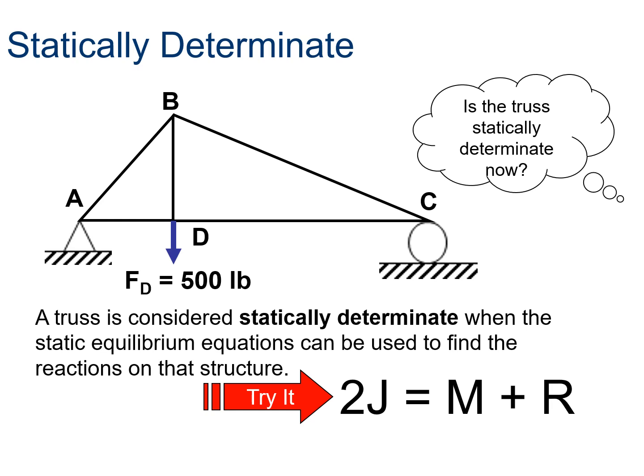now you have the same number of beams, 1, 2, 3, 4, 5, so M is equal to 5. And we have the same number of joints, 1, 2, 3, 4. Now the difference here is in the number of reaction forces. Remember that with this fixed one, you can either go left, right, or up and down, but you really got to pick one, X and Y. So there's movement in either the X or the Y direction. So there's two different reaction forces. You can't go up and down is the point, right?